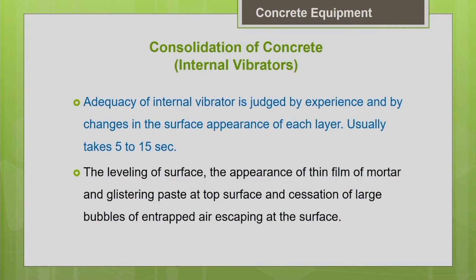If he is an experienced person, he can make a guess whether the consolidation is done or not. Your surface will appear very level, and the air bubbles which come to the surface will stop coming to the surface. That is an indication that consolidation is done. Also, you can see the appearance of a thin film of mortar and glistening paste at the top surface, which indicates that the consolidation is done. So, these are the indications that the consolidation process is complete.